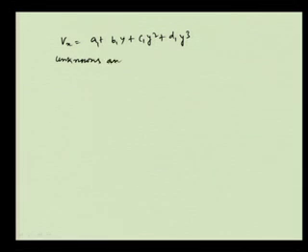We have seen it is a kind of nonlinear velocity profile. So, if I say in a boundary layer, Vx is equal to a1 plus b1 y plus c1 y square plus d1 y cube, how do we get the velocity profile? We can understand this is a third order polynomial with 4 constants, unknowns: A1, B1, C1 and D1.